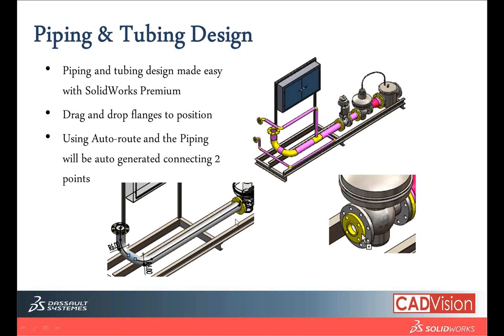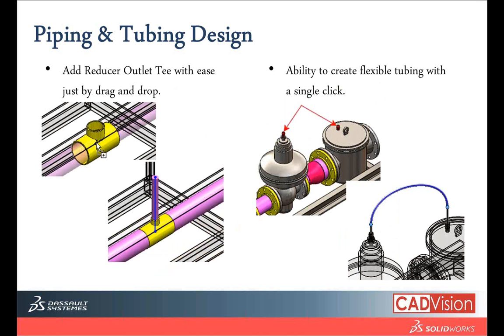And so the next thing will be selecting point to point for where you want to join them together. So let's say if you have a chamber, a big box, a tank where you want to join 2 points together, all you need to do is click on auto routes, click on the 2 points where the pipe will join, and it will automatically generate one pipe, one tube, joining 2 flanges together. We have alternates. It has capabilities of choosing an alternate path and manually adjusting all these paths, depending on your desire and what outcome you want.